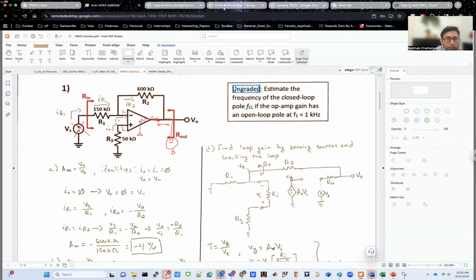So you have a ground, and connected to the ground, there is a zero resistance. So an infinite amount of current flows through that zero resistance path to ground. Because there is an infinite amount of current coming out of the voltage source over here, any finite voltage source divided by infinite amount of current will give you zero resistance at the output. So your Rout is going to be zero, which will be the case if you have an ideal op amp, and the point that you're looking into is basically the output of the op amp. So that is always going to be zero, because there's always going to be this infinite current, zero resistance path through the output of the op amp going back to ground.